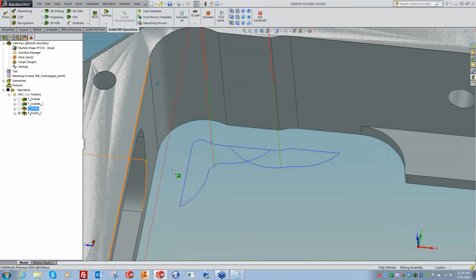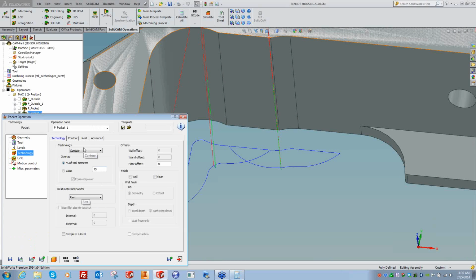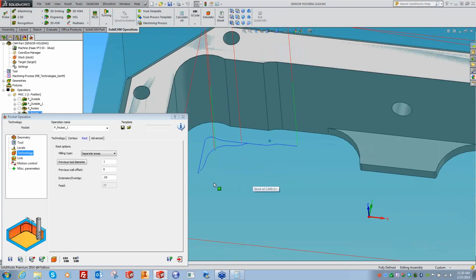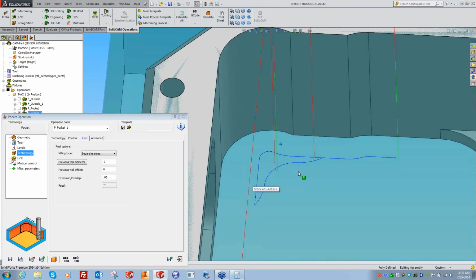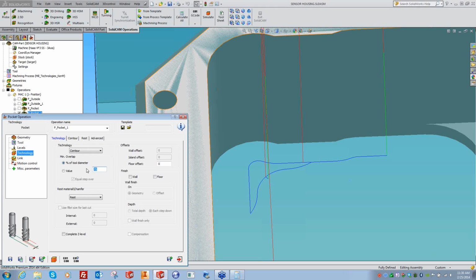And now, by the way, it's doing this, and it's got that extra overlap right here. If you want to kill some of that overlap, let's do, where's my overlap? Where was I at? It's right in here. Let's just do 50. Notice how it gets smaller. We'll go with that. And we have 2 cuts right here, but actually I want it to do more cuts in there. So we can just change this value. This is an overlap, so it's only 5% of the cutter is cutting. Now I get extra cuts in here.